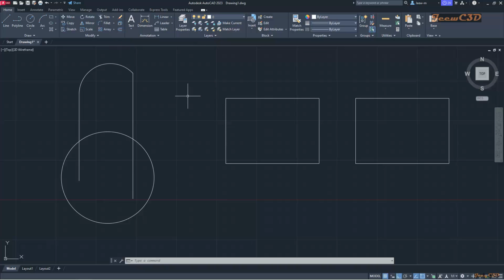Likewise you can use the command line shortcut keys to launch the commands through the command bar instead of going through the ribbon. So that is about accessing the commands through the command line. So I am attaching a resource file where you can get most of the command line shortcuts to initiate the commands in AutoCAD.